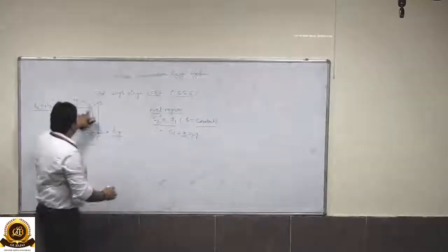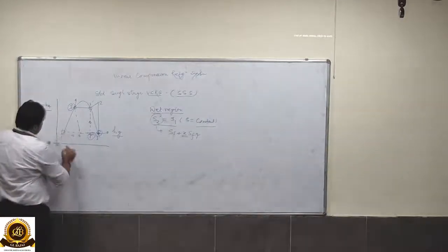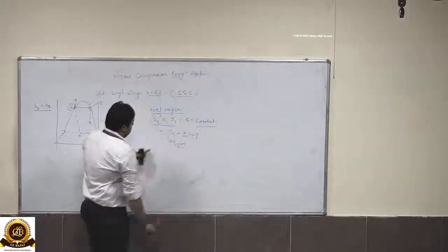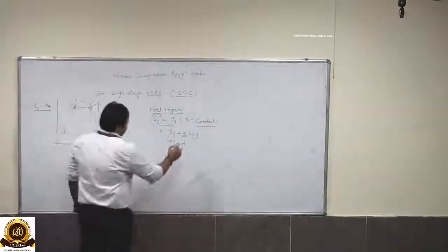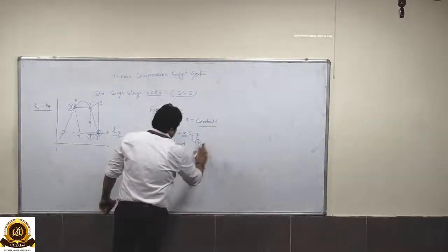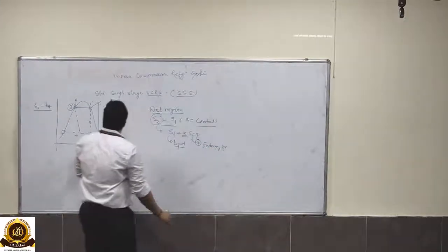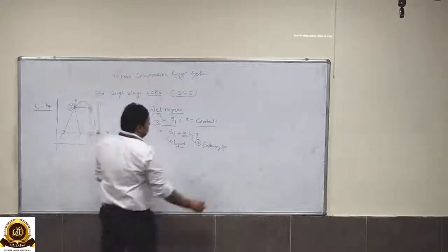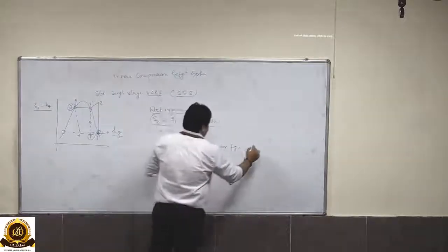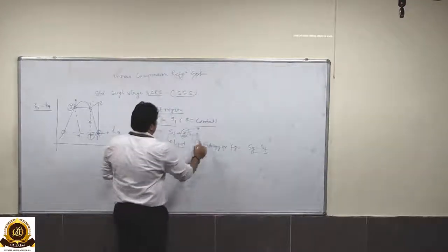We know the value of S2 dash. From the steam table we can read the value of SF, which is the entropy of the liquid at this evaporator pressure line, and SFG, which is the entropy for the two phase or vapor dome region. This is also the difference of Sg minus Sf. So we can calculate the dryness fraction value over here.